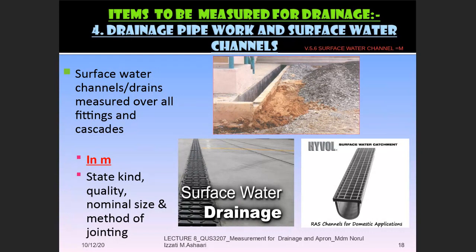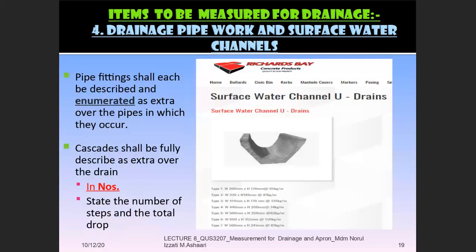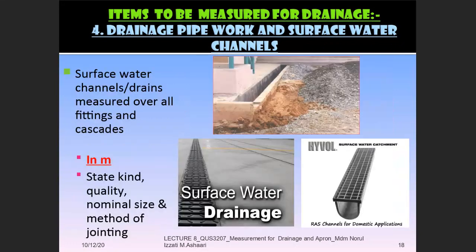Again, you can take the length equal to the length of your trench excavation, or equal to the length of your beds just now. Okay, beds. You have to write the size, the kind and quality, and don't forget the jointing method. If you look at your SMM, the second last sentence says including the size and method of jointing. So you have to measure that method of jointing.